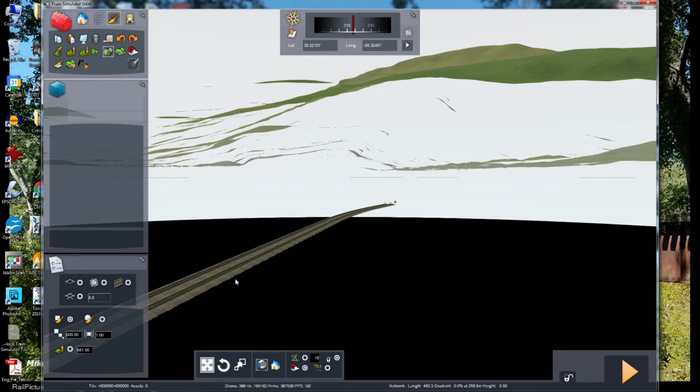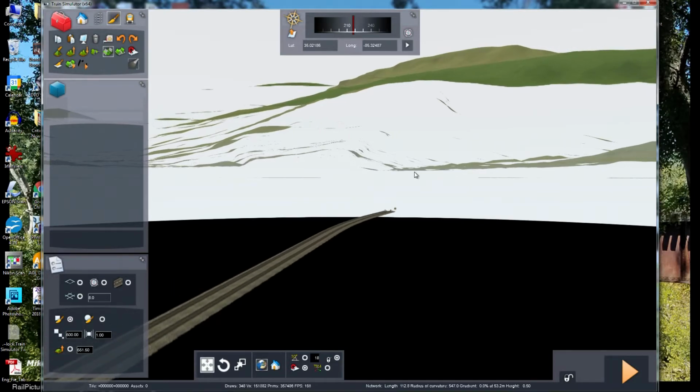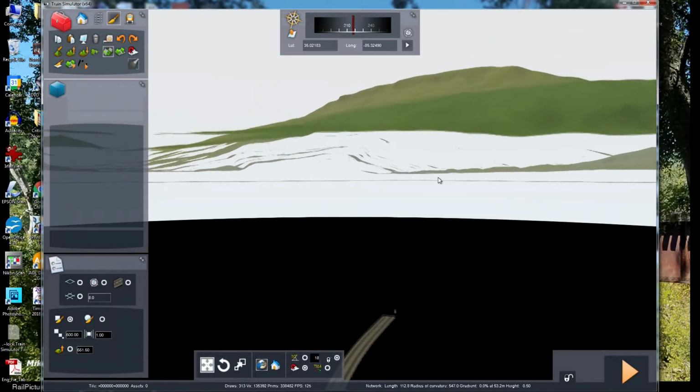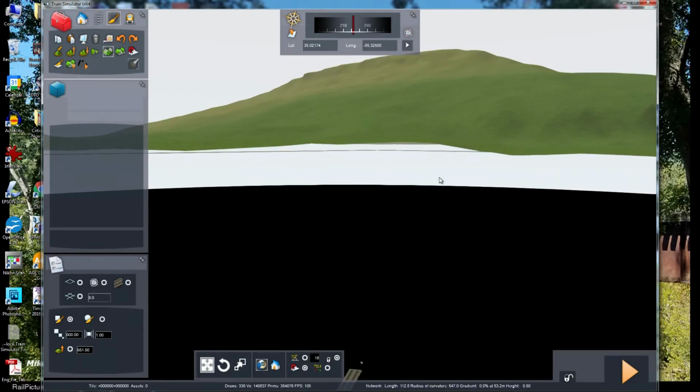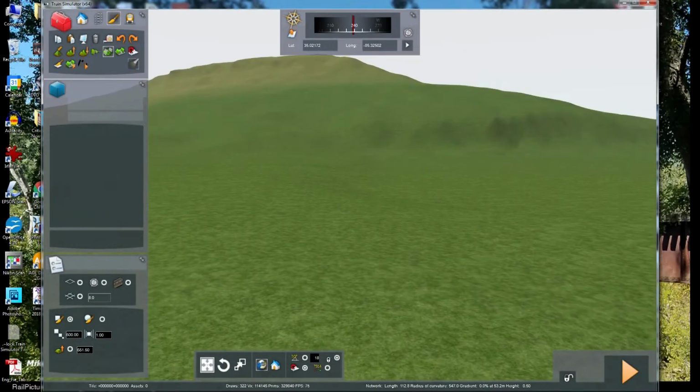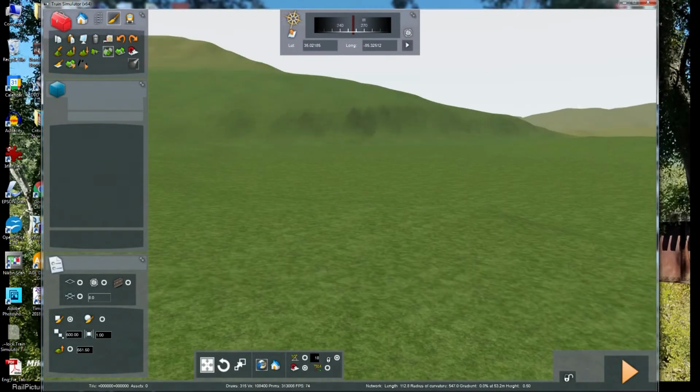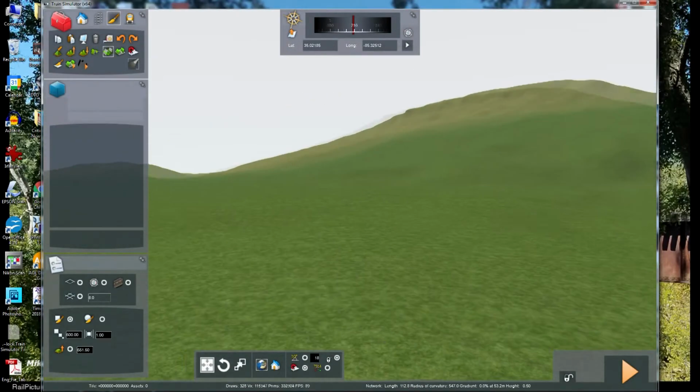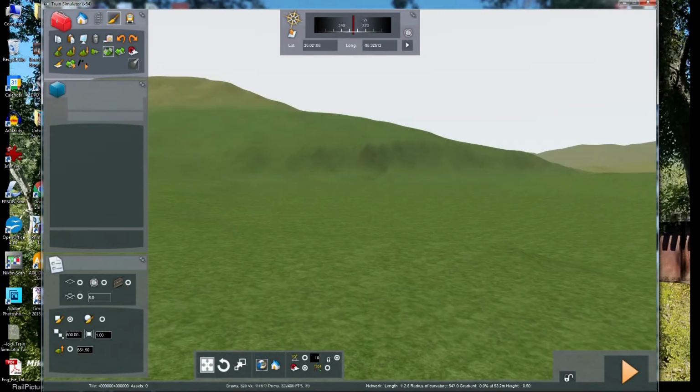So here we are. The terrain level has now gone up to actual height in Chattanooga, and we're going to go up now and see what we have developed. By clicking the control, the up arrow, and the shift key, we quickly are up. Now here you have Lookout Mountain in Chattanooga, Tennessee.